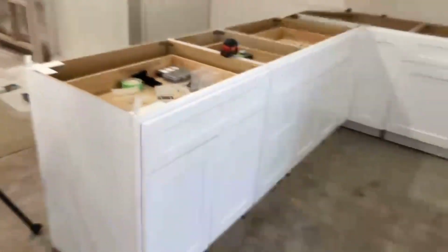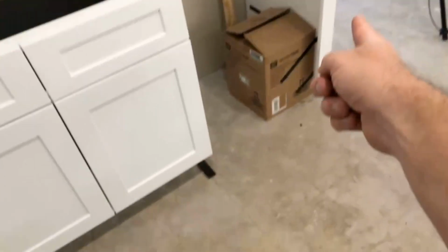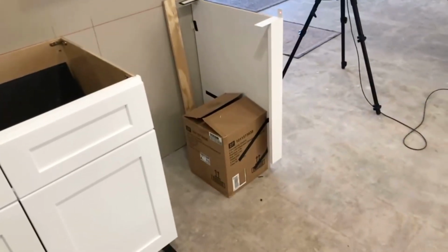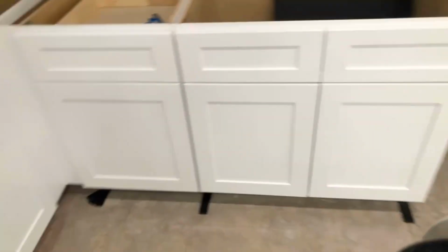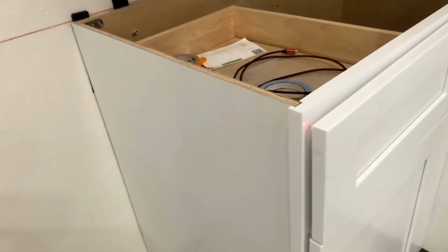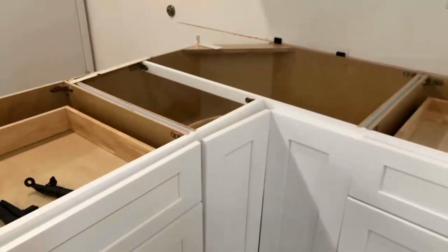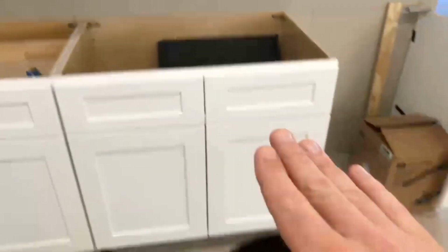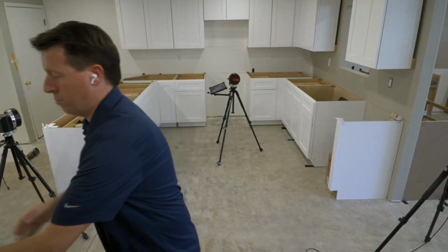Okay. So now that I have targets set up, sorry if anyone's getting motion sickness here, but I want to give you the point of view. As I aim the laser, I want to make sure I have something to hit all the way around the room. All my cabinet faces, I want to make sure I have a clean point to hit on the range opening and along all of our walls, okay? So if I don't have a good view, before we've set the plane, we can still pick up the laser and move that. Let me switch back over here.